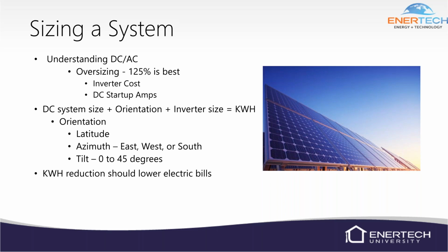And if you used a 10 kW inverter on a 10 kW DC, you're only going to make maybe 500 kilowatt hours more a year. So it was very advantageous of us to go ahead and design in a 7.6 inverter for less money. It gets more startup amps in the morning to get the inverter turned on.